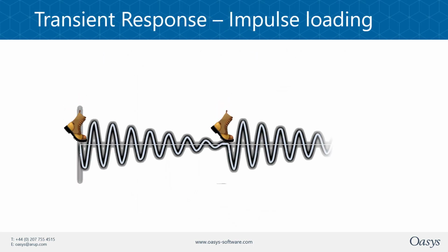As well as resonant responses, you can also get transient or impulse responses, which is normally on high frequency structures, where the vibrations die off before the next footfall lands. Thus, it's the first peak acceleration that is calculated, and the damping has little effect on this result.